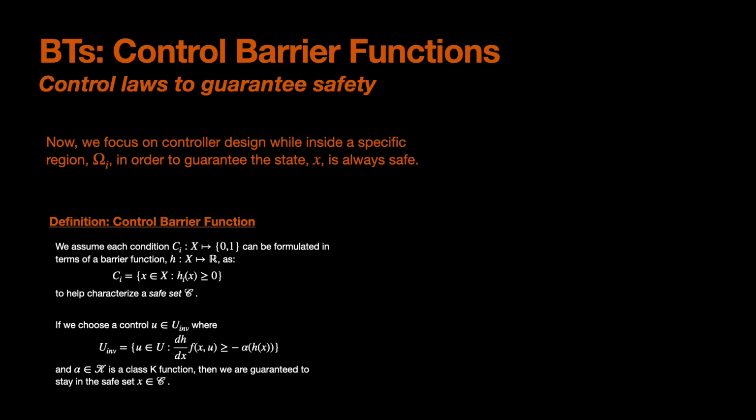Formally, the definition of a control barrier function is given here, and all it says is basically a relationship between control and the edge of some function that we care about, primarily our barrier function h. Our control will throttle or limit the control effort into the dynamics such that we can never push past that barrier h.